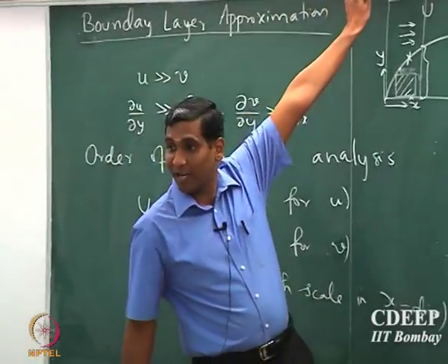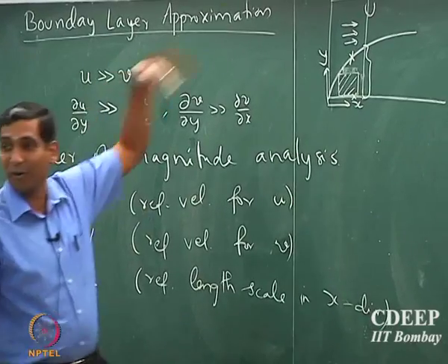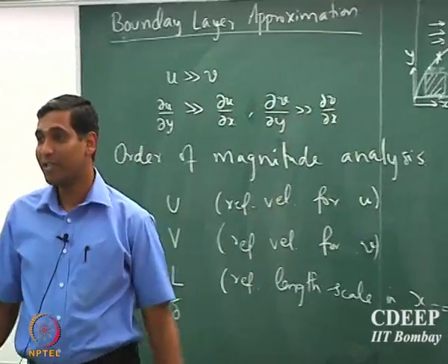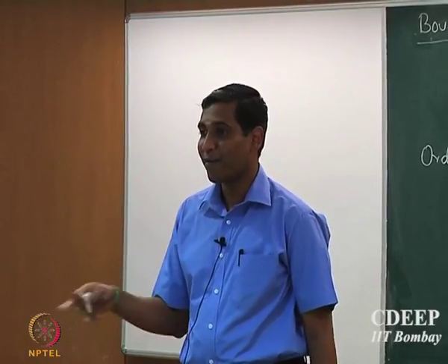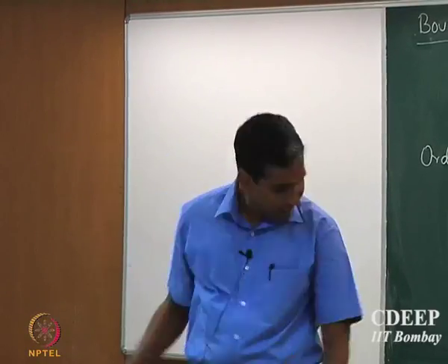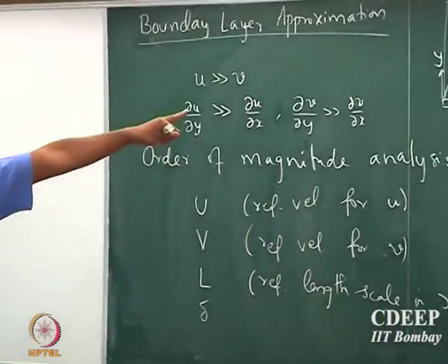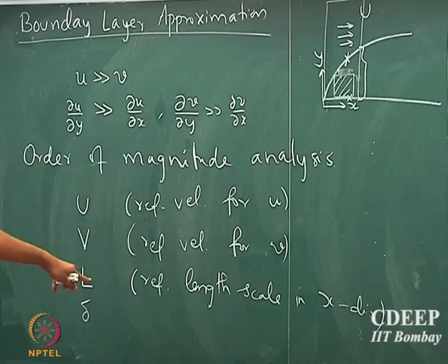Well outside the boundary layer? No, it will not be. You will not have mass flux well outside the boundary layer, which means that the fluid is no more moving in the x direction. You're going to have a net pressure gradient in the y direction. In fact, you're going to see from order of magnitude analysis that the net pressure gradient in the y direction has to be 0. We'll see that in a short while.